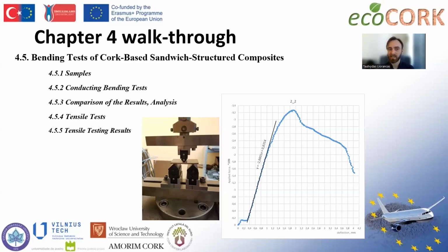The tensile testing results showed us that when we talk about tensile strength, the core material is not so significant because the tensile strength is mostly associated with the reinforcing material on the sides of the sandwich panel.